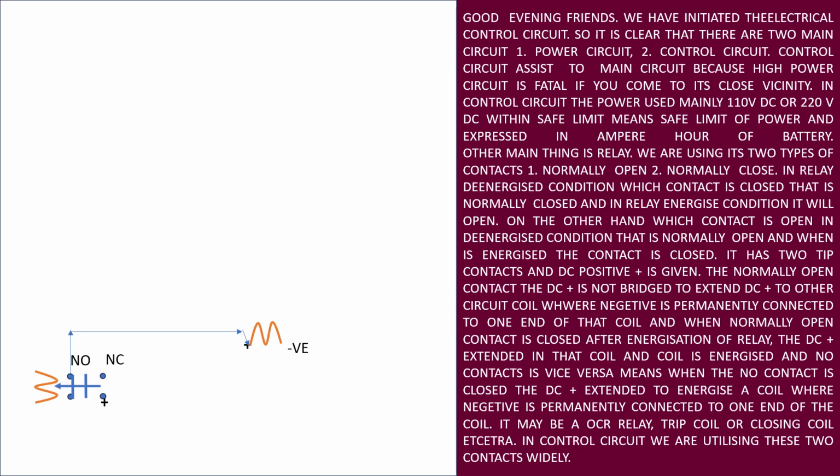So it is very important. So what we have done in the capacitor tripping device, we have provided a capacitor which, when DC supply is available, is connected through the close contact of the relay. With the relay energized, it is charged, fully charged.